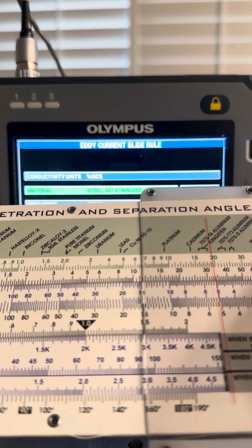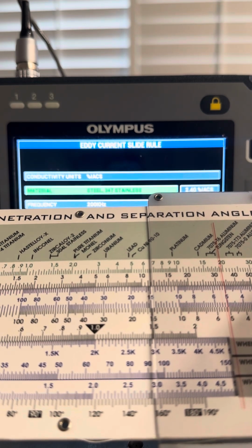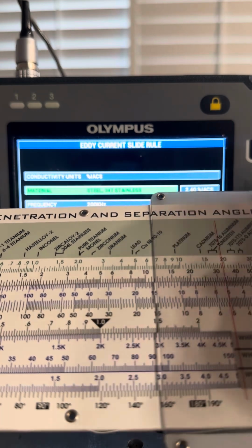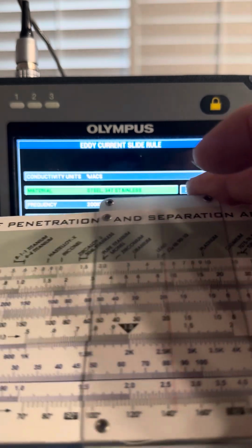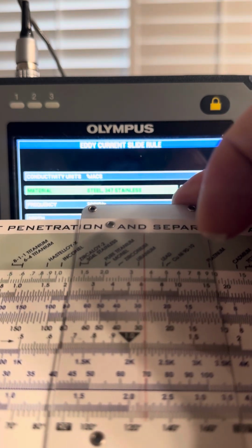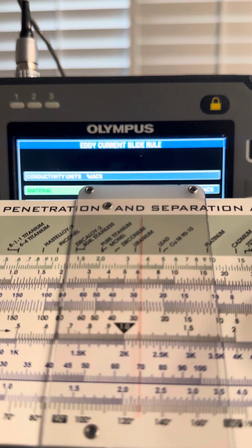So that would give you a 90-degree separation between your shallow ID and shallow far surface indications. Now, if I was going to calculate F90 for tubing, instead of setting 0.8 at the far surface, we just use 1.1 at the far surface. So another example, we're going to use Inconel.